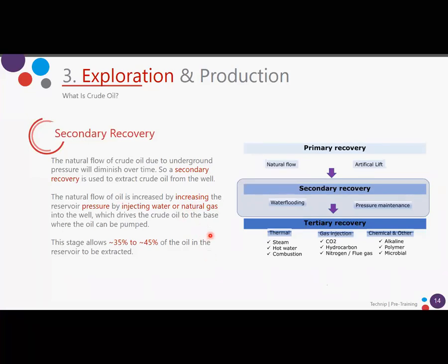This is what we call the secondary recovery, that is, to increase pressure. So we can increase the pressure with water or with natural gas. How much crude can we recover in this secondary recovery? Up to between 35 to 45% of the oil in the reservoir. So the secondary recovery is based on increasing the reservoir pressure.